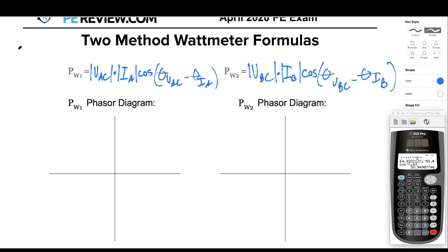For a balanced and positive system, what's my A line voltage? Give it to me in the chat. Give me the proper two subscripts. V what? For a balanced and positive system, it's going to be VAB, right? Next is what? VBC. And last, VCA, right? These are the line voltages for a balanced and positive system.